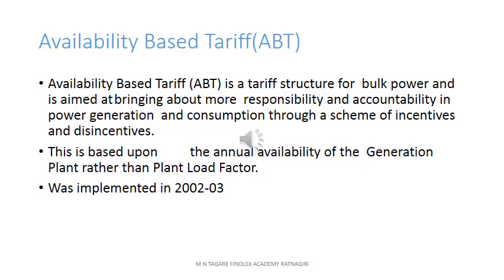Because of these voltage fluctuations, so many problems were created in the grid. Similarly, because of frequency fluctuations, sometimes some of the units used to trip on under frequency or over frequency. Because of that, it further led to tripping of another generator.